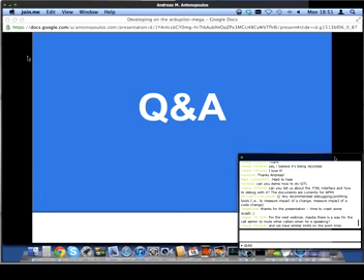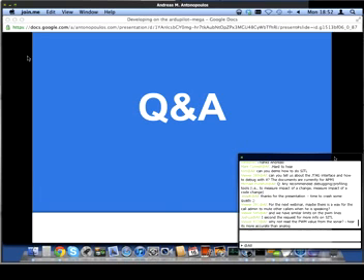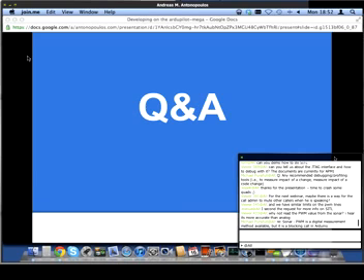That's right, Andreas. It's also that we can read from the analog to digital converter much more rapidly. That's because it's a much lower overhead to read from the ADC, so we can read at maybe 100 hertz or so on the ADC using an interrupt driver, whereas the interpretation of the bytes required to read off the serial port would slow down the reading a lot.